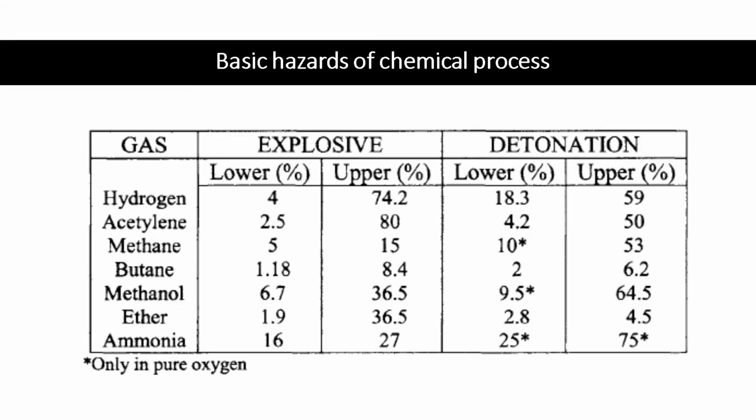Let's take the causes of chemical plant hazard and see how they relate to hazard study methods. This gives us an idea of how a combination of conditions should be tested to relate the conditions that could cause an accident. Let's review some causes of explosion, fire, and toxic emission. Cause of explosion: to create an explosion, it's necessary to have together an explosive mixture or material and add an ignition source. An explosion inside a container is said to be confined, while an explosion outdoors is unconfined.